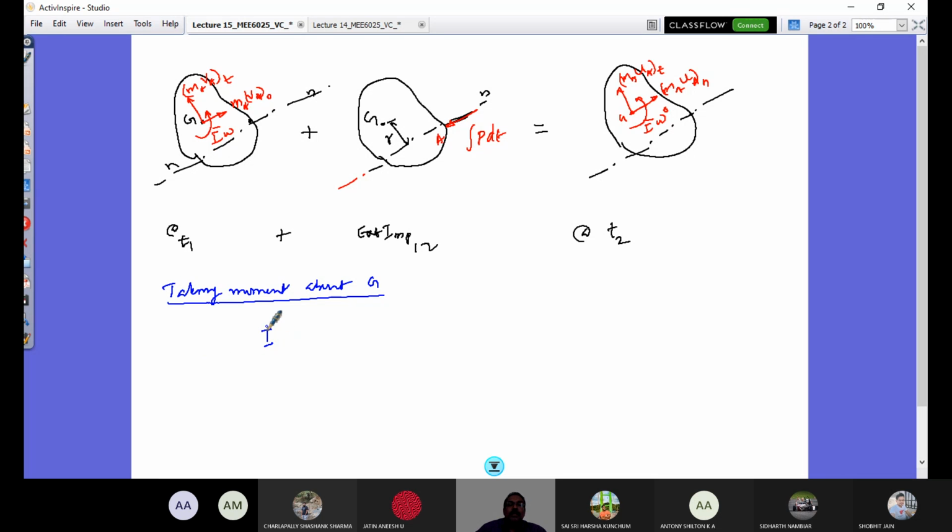So I would have only I bar omega plus, and here you see I have this direction like this, and the rotation is clockwise. So our convention here of the moment of momentum is counterclockwise positive, and here that is going to be minus r times integral p dt. R is the perpendicular distance between this line of impact and this point G. This would be equal to, again, these two forces are at G, so that won't participate. So I would have only I bar omega naught. So this is equation number 3.